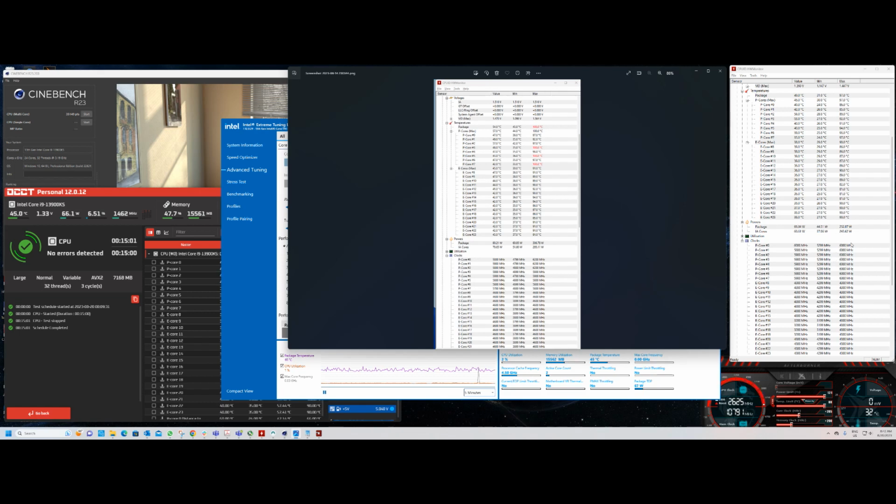As for overclocking, I decided to readjust things. I'm still making final adjustments, but for stability for this video, I decided to at least get to a specific number. For the P-cores, I was actually able to get them all set to 6,000 megahertz, while the E-cores, as you can see in the old data, were about 4,600, while here they're about 4,300, which is not much difference, guys, regarding benchmarks.